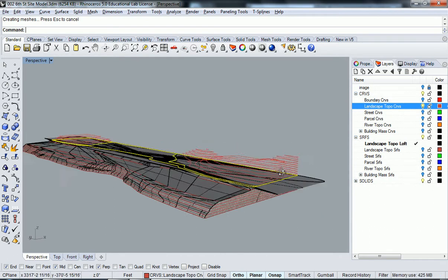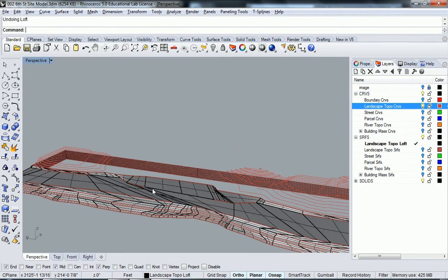And that's not going to work for us. So lofting has its reasons and times to use it, but you can see right here it became an issue, right? So if you were trying to loft all this and then you got to this point, you'd be like, okay, well, what do I do now? So maybe lofting wasn't the best option.